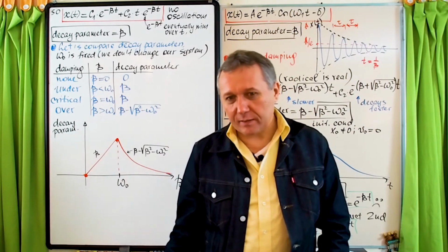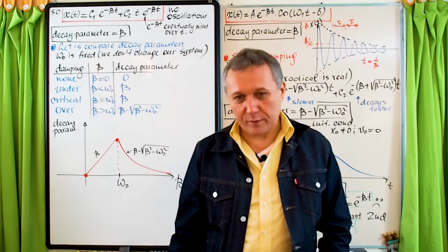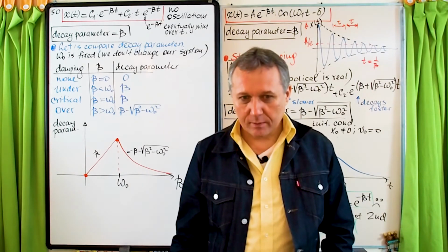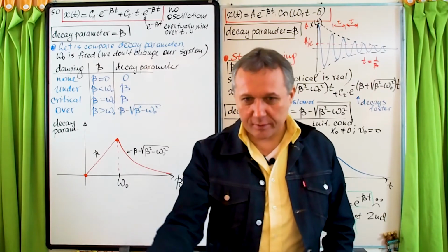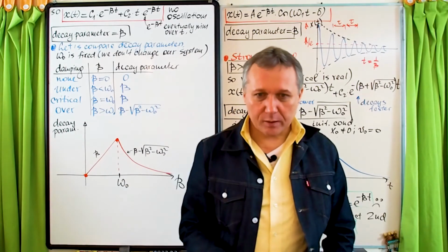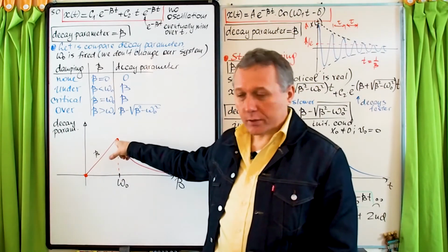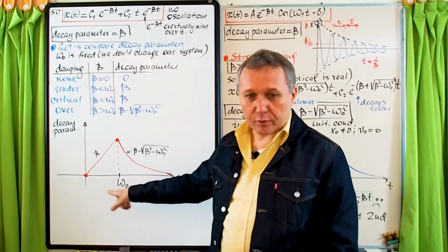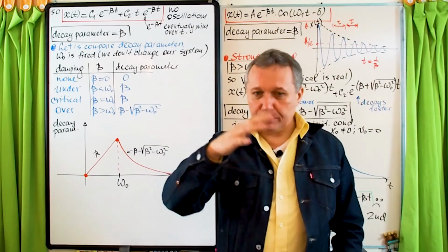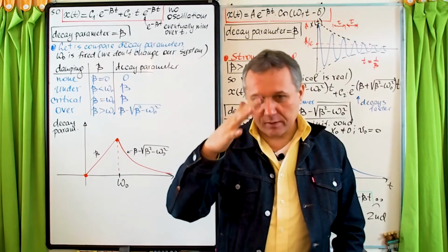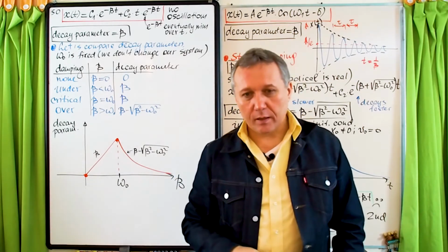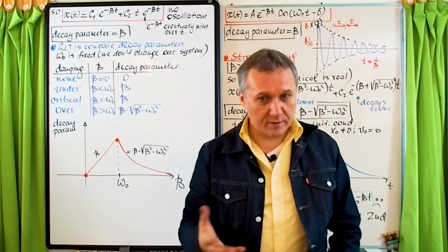If it was designed like this, that voltmeter would fly out of the window in no time, in my case, because it would be really annoying. You want to see the results, and it keeps oscillating. You need to use critical damping so that the needle is displaced maybe once from the actual reading, and then goes to the actual reading as fast as possible.